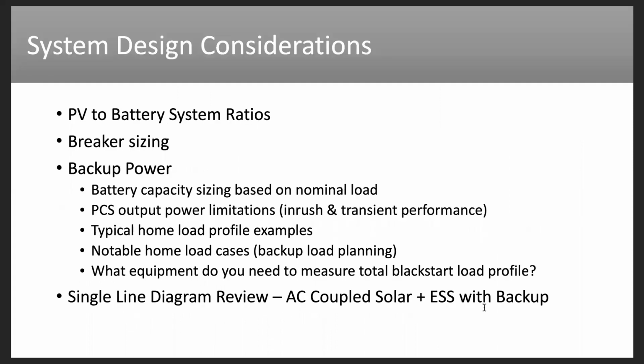As an FYI there. So as far as system design considerations, we're going to be looking at the PV to battery system ratios, breaker sizing, and in backup power, looking at battery capacity sizing based on nominal load. We'll look at PCS output power limitations. Both inrush and transient performance will be covered.